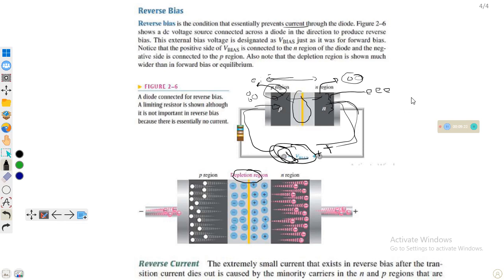A very small current of microampere order is constituted in the circuit. So in reverse bias we have a current, but it is because of leakage current. This is known as leakage current, because minority charge carriers, for example electrons, cross from the P region to the N region, and these electrons are very few in number. Therefore they are actually leaking from one region to the other.